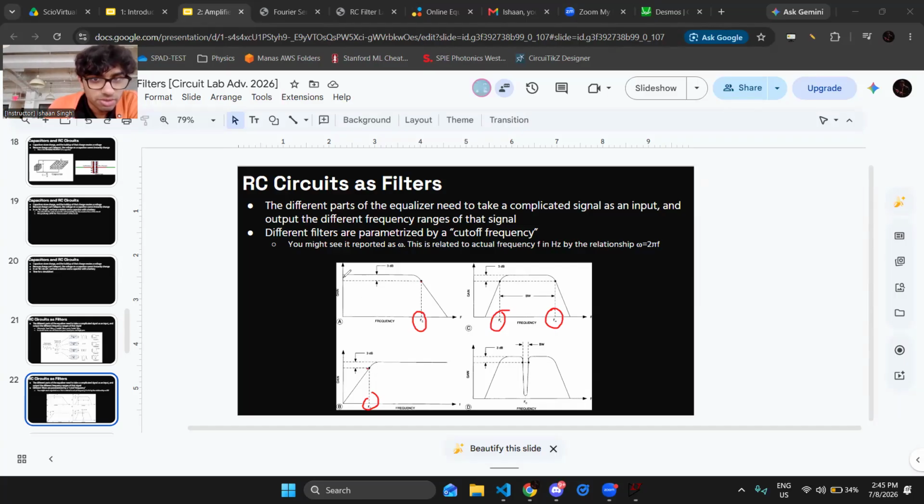So, what kind of filter is this one right here, in the top left corner? Low pass. Right? And if I have a lower low pass filter, it's going to look like that. Is the curve steeper? Lower meaning lower cutoff frequency. So that's just a horizontal shift. Steeper relates to the order of the filter, and we'll talk about that.